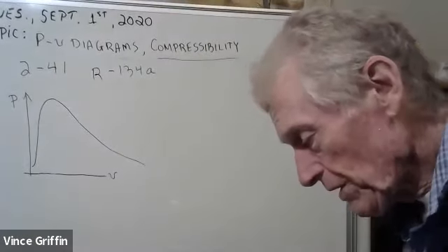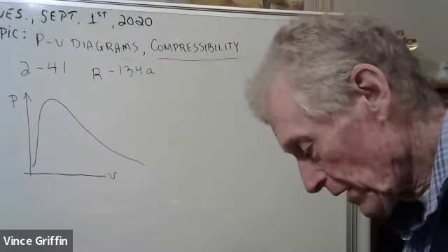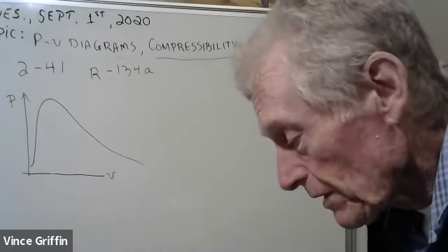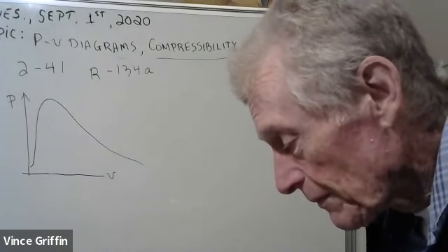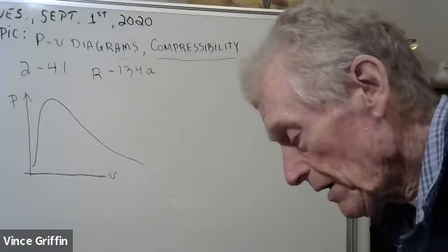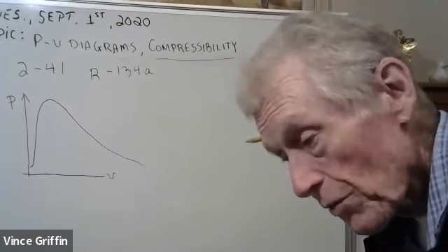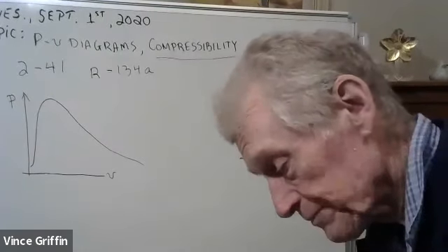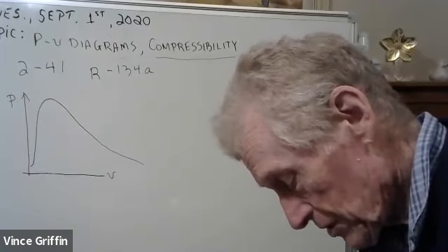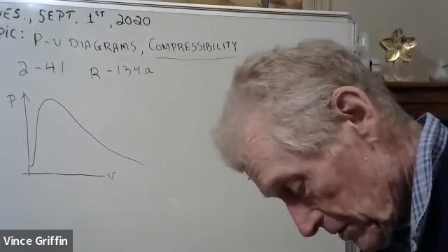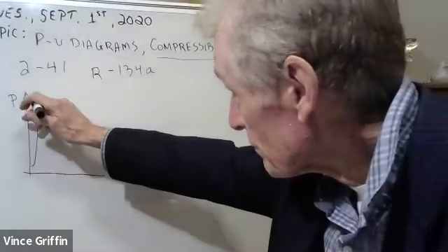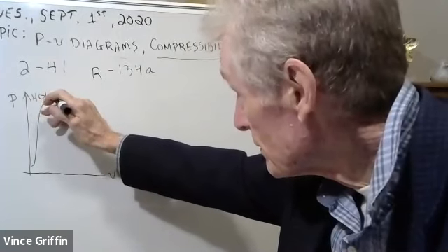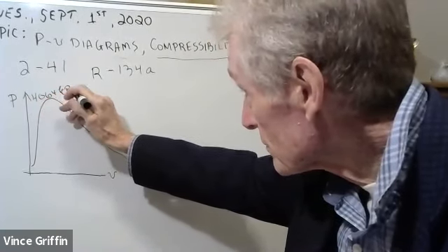Now go to the back and help me find R134A. Let me dig around in the back just a minute. Yeah, found it. Now I always go to the vapor dome, or what they call the saturated chart table first, and see the top pressure up here at the very top is 4,064 kilopascals.